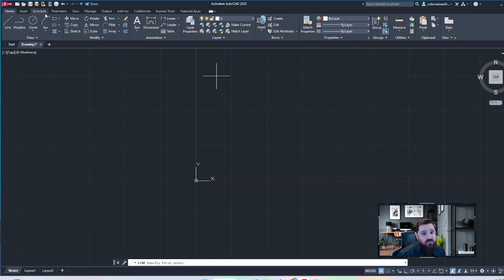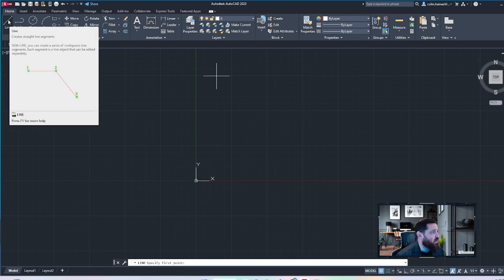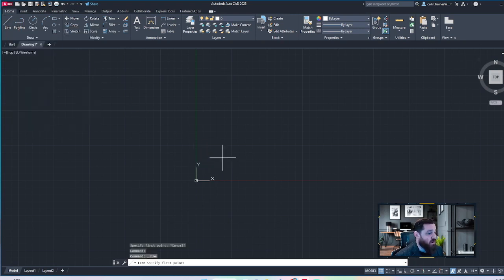And if that confuses you right now, don't worry about it because we're going to show you how it looks in practice. So mine by default was set to work with absolute coordinates. So no matter what, the first thing you type in, your start point will be an absolute coordinate because it can't be relative because there's nothing for it to be relative to. So we're going to type in 1,1, enter. And now I'm going to stay with absolute coordinates and I'm going to hit 2,2, enter.